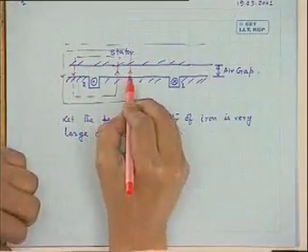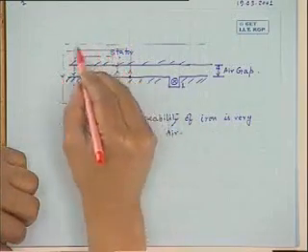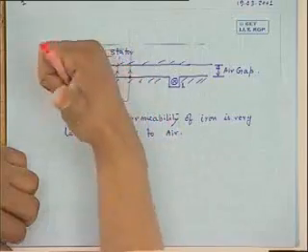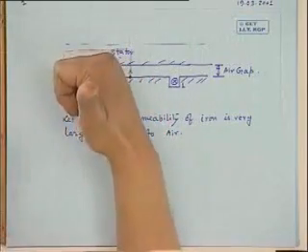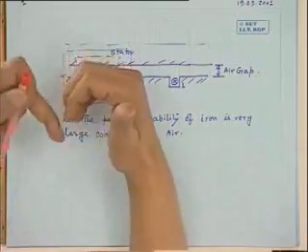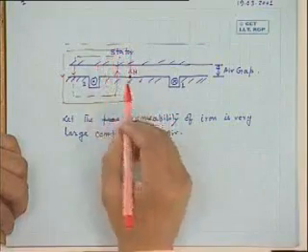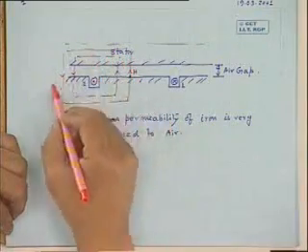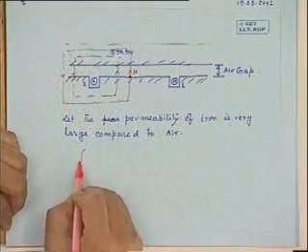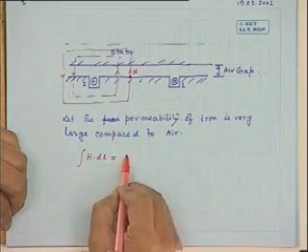Suppose I want to find out the field at this point. So I consider a closed line of force circuit, the direction of which I find out by your right hand rule. That is, you put your thumb along the direction of the current, and the other fingers will give you the direction of the field. Now suppose H is the field here. Then H into L, you know, H integral dL is what? Current enclosed.